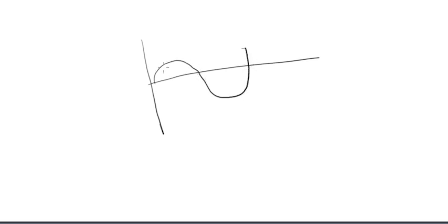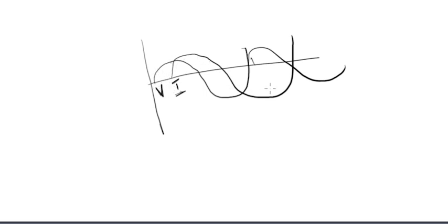So we have it like this. We have the voltage, we have the current. We know half of this is pi. Both of them are moving, so which one is leading? This is I. This is going to be the position of I, leading by pi over 2. Then this is the position of V. I is the one that is leading by pi over 2 or 90 degrees.